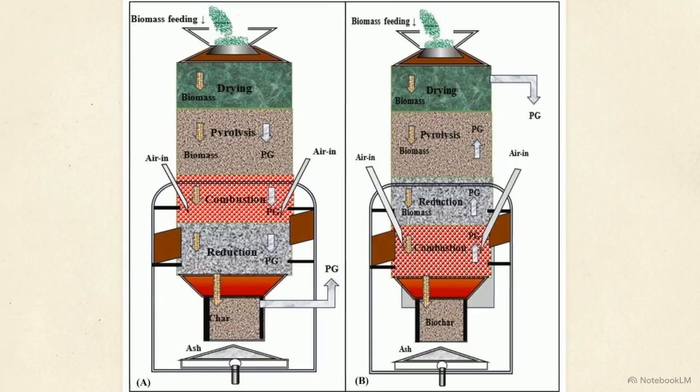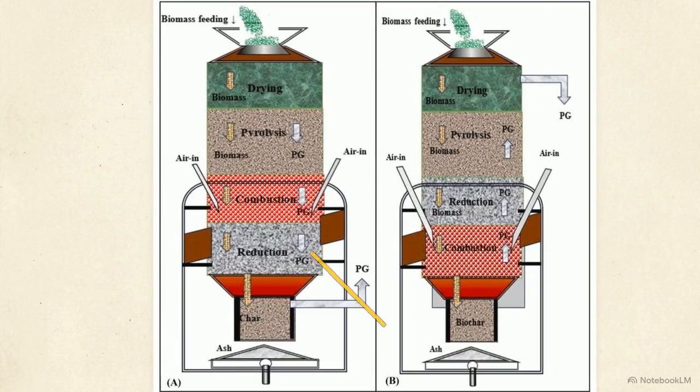The downdraft configuration reverses this mechanic. The gas is forced downward through a high-temperature charbed. The intense heat successfully cracks those heavy tars, but significantly limits the overall cold gas efficiency of the system.